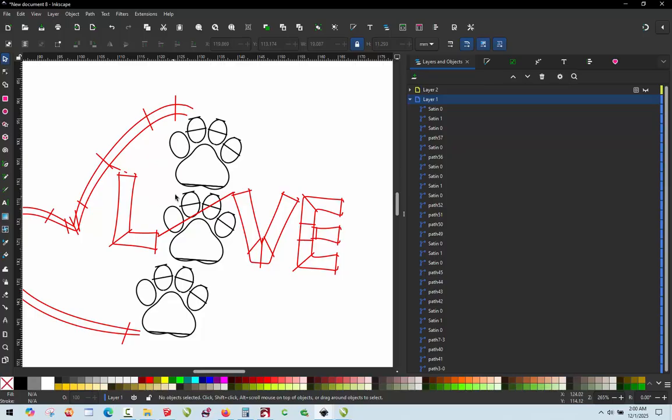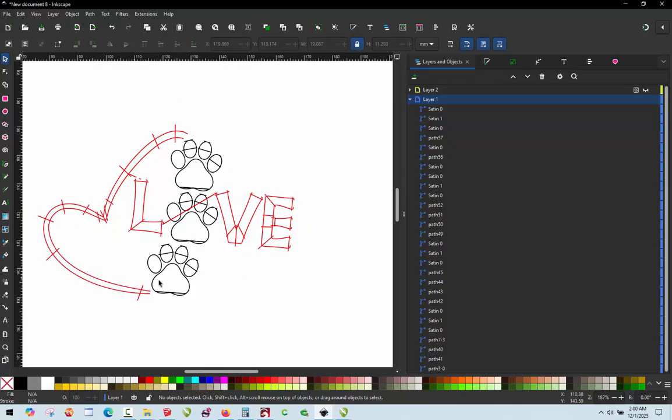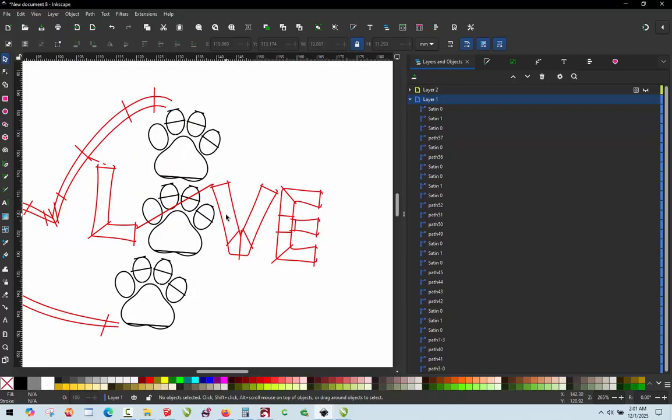And trust me, if I'm doing 100 polos with that logo on there, saving 100 thread trims is like saving, you know, the way it kind of works is for every thread trim you have in your design, you're adding an extra minute. An extra minute for the machine to slow down, trim, and start back up again. And it's unnecessary wear and tear on the machine because it's got to do all that. It's just not necessary. Trust me. Better to pluck it afterwards because it only takes a second.